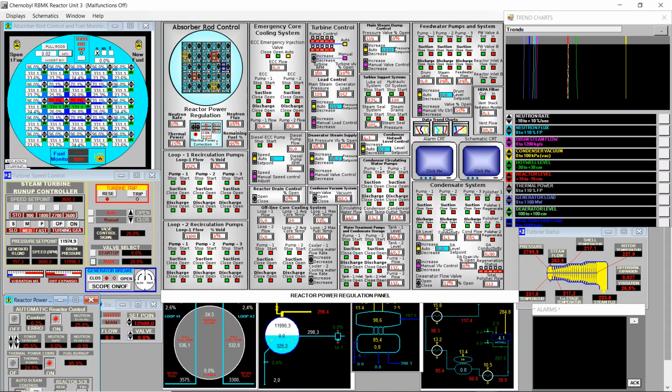Okay, so there is nothing else to do. From here to 100%, it's just increase power step by step, slowly, checking all the parameters while doing so. And we did this in 34 minutes. Let's see the total time that it takes us to bring this up to nominal power. I will go to 35 now, or 40, and then stop a moment.